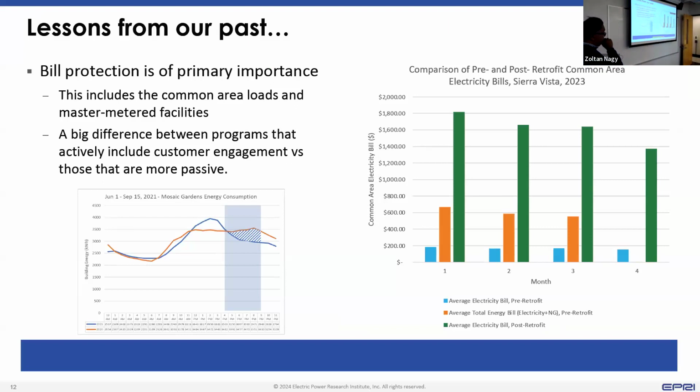Because what you're trying to do on the left-hand side is there is a period of high time of use rate during the middle of the day between 4 p.m. and 9 p.m. And you're trying to reduce energy use at the time. So we used a combination of messaging to the community through an app, and then solar and storage. So you flex the solar and storage, you flex the battery in the community, and then you can see how you're able to get a reduction in energy use during this period of time, but then it shifts the energy use ahead of time. So this is actually good because this is the time when solar is available. And so it's great.